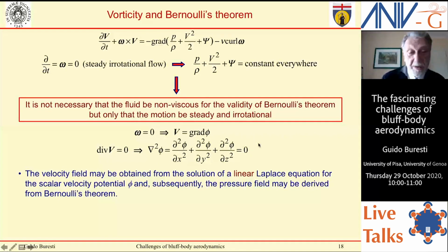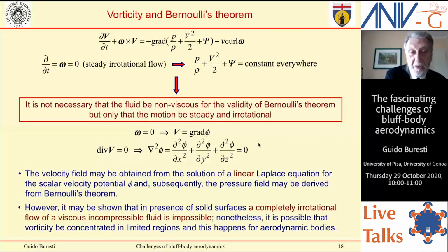Now, however, you may show that in the presence of solid surfaces, you cannot have a completely irrotational flow. Nonetheless, it is possible that vorticity be concentrated in limited regions, and this happens indeed for aerodynamic bodies, and is the origin of the simplified procedure for evaluation of the loads for an aerodynamic body.